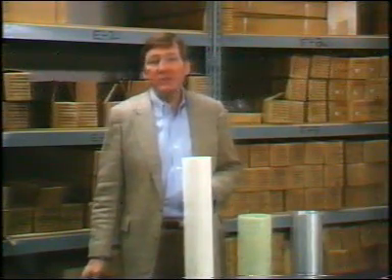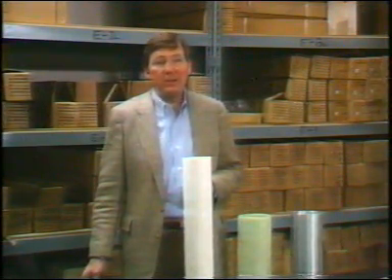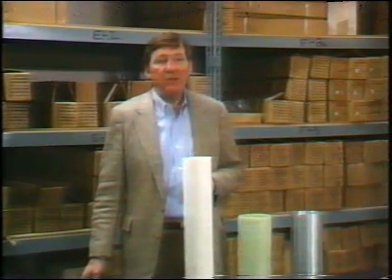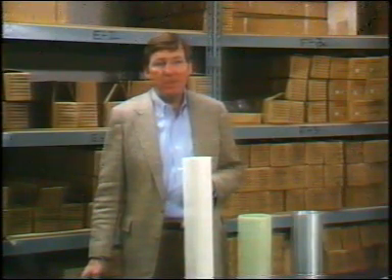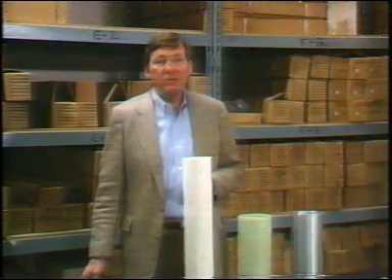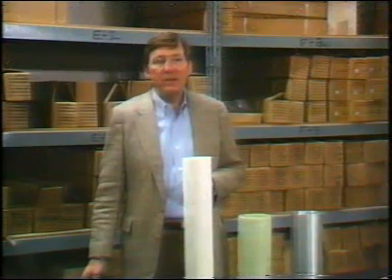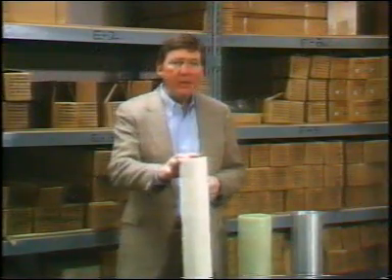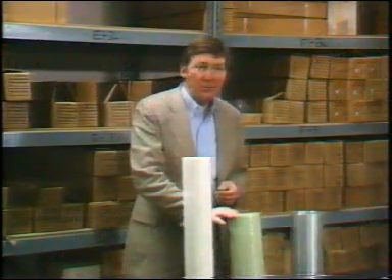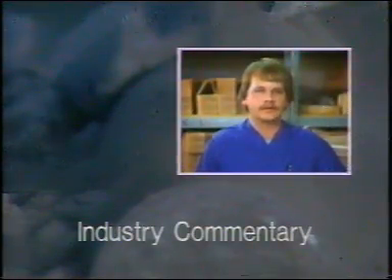In order to retain samples intact, especially unconsolidated samples, it is possible to use special inner barrels or liners. Thus, rubber sleeves, plastic liners, fiberglass, and aluminum inner barrels may all be used to retain unconsolidated cores. When the core reaches the surface, it is retained fully protected within the sleeve or liner as it is removed from the coring device and delivered to the laboratory. Here we see examples of a rubber sleeve, plastic liner, fiberglass inner barrel, and aluminum inner barrel. In Canada's tar sands, we typically use plastic liners and freeze the core in the liner at the well site.